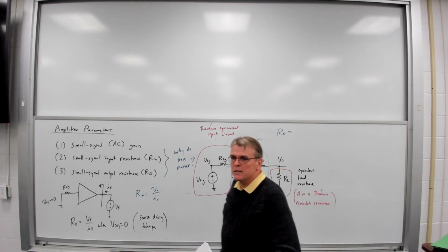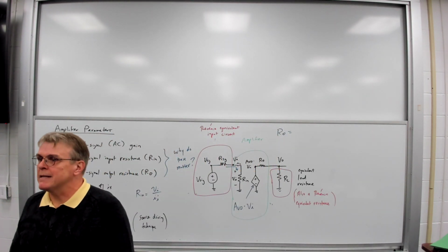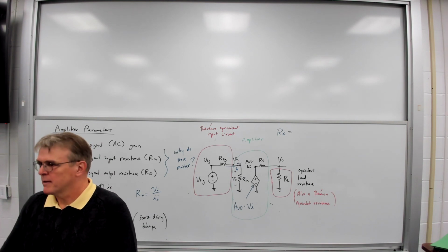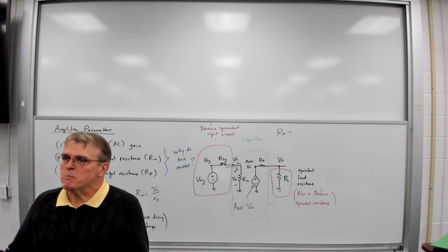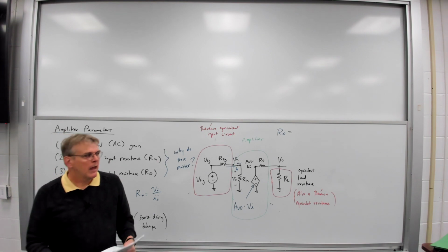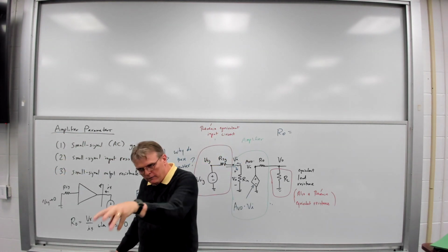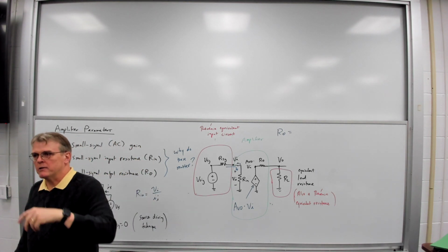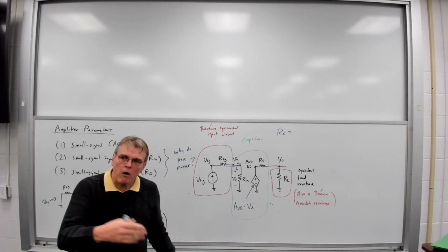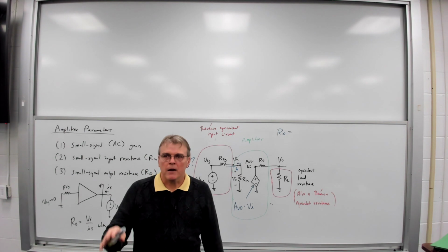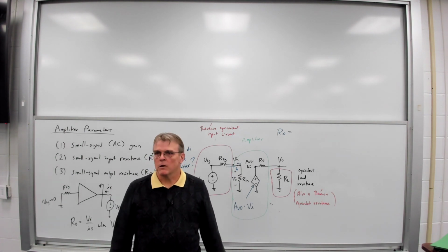So, having looked at this, let's now do some analysis of those amplifier topologies. We're going to do some small signal practice with these. Now, on these first initial topologies, guys, I'm going to go through all the equations and work them out explicitly. As we move on through the class, I'm not going to take time to write all the equations for the small signal diagrams.